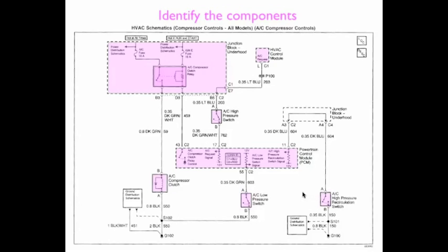We have our AC high pressure recirculation switch. Now this switch is open, so at rest it is open, as opposed to these which were closed. So things coming to this switch will stop because it is open. We're going to talk more about this at the end of the diagram. And then there's another part of that junction blocks under hood up here.